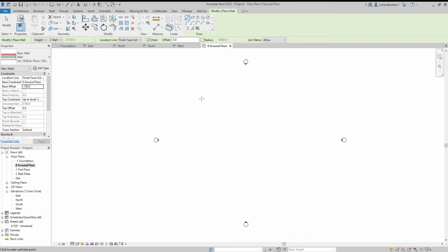Now I'm going to do the actual house. So I'm going to put the cursor somewhere over by here between these cameras. Click. I'm going to go across 7 meters. So you can either move it and find the 7 meters, as you can see with the writing, and click, or you can just point it down and type with the keyboard the dimension and then press enter. So the house I am doing is 10 meters by 7 meters.